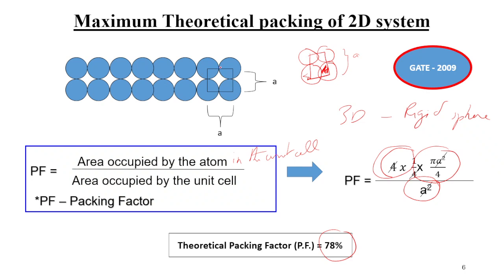The unit cell is like a geometric structure, and when we draw it on this group of 4 atoms, the entire atom is not covered. We are taking the center points of the atoms for ease of calculation. That is why, when we take the center points, we can find the radius of this particular circle. So this will be 1 r here, and another r here.